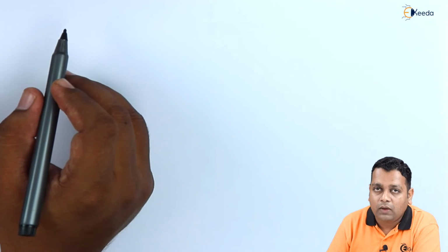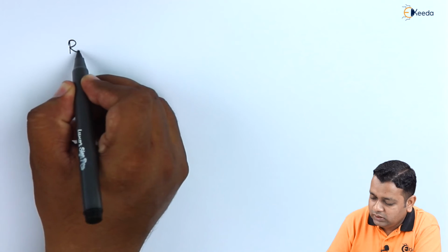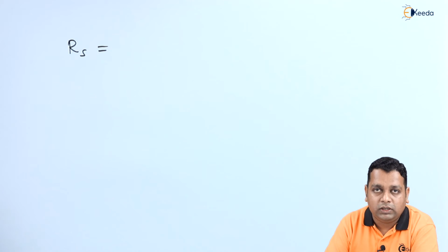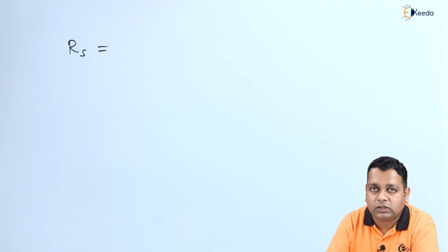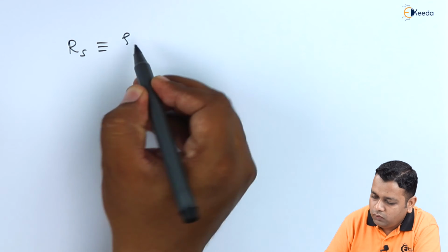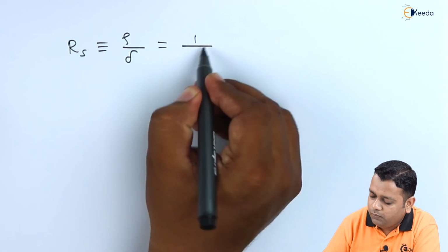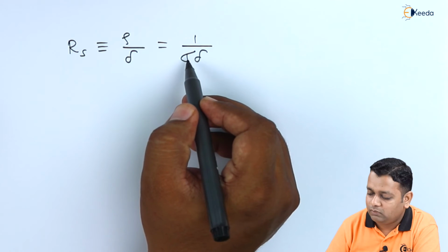So now instead of having the earlier equations representing the power loss, we can also make use of a surface resistance denoted as Rs. For a practical metal material having higher conductivity, it gives us the surface resistance expressing how much depth of penetration we can have into the walls of the waveguide due to the microwave propagation. This is basically related to the ratio of rho to delta, where delta is called the skin depth. It can further be expressed as 1 upon sigma into delta, rho being the resistivity, the inverse of the conductivity sigma.